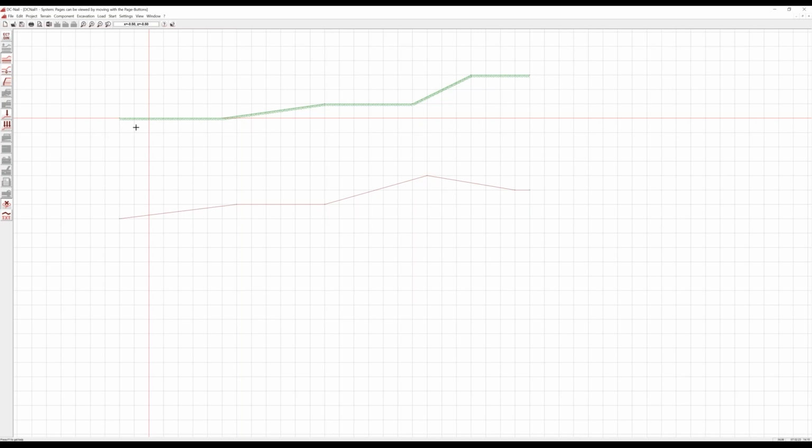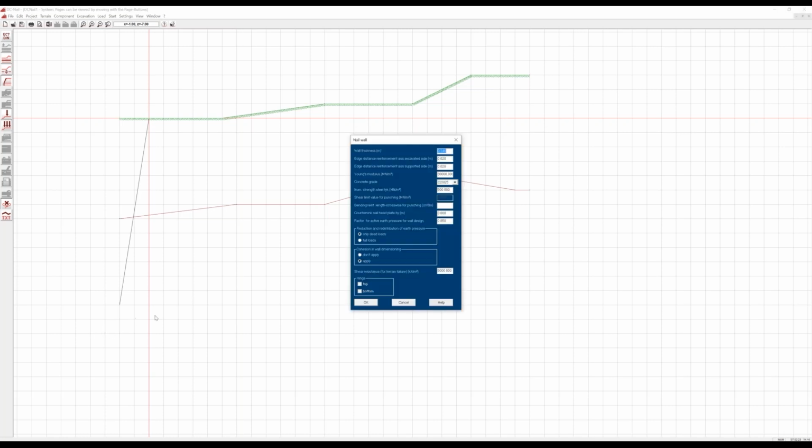And then, if we have an excavation at this side, we define the shotcrete wall, which holds the surface here and which is fixed by the soil nails. So I can enter the wall here. Mostly it's inclined, for example, under 80 degrees. And these can also be several sections, or I finish this with the right mouse button. And then we have the parameters for the shotcrete wall.